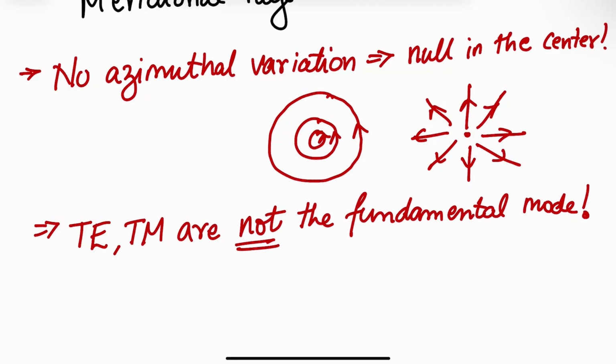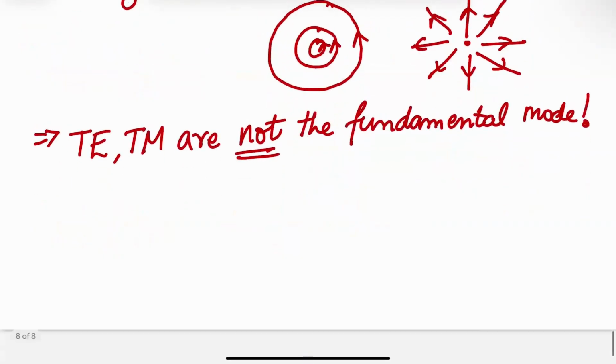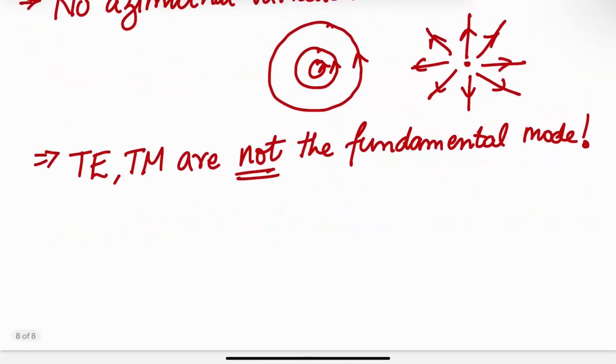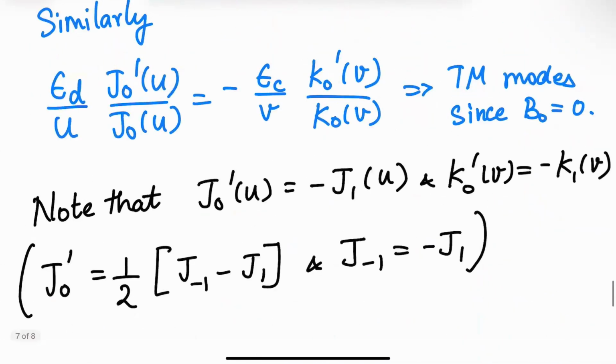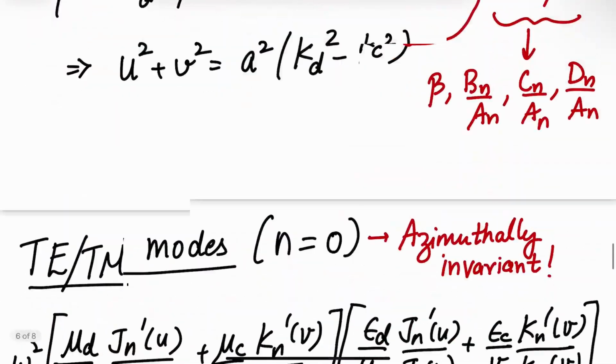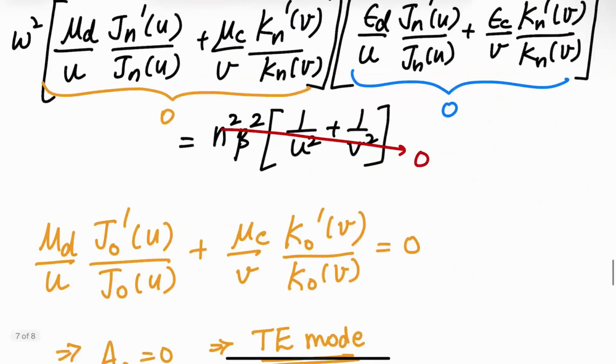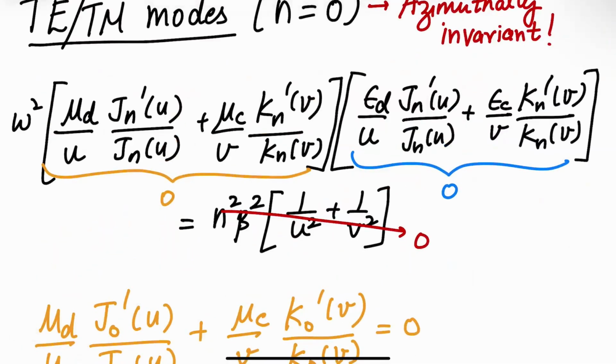And the reason behind that is that all other modes are in cutoff, so you have a bandwidth over which only this mode propagates, so it's very easy to excite it, right? And have only that mode propagate. So those fibers are called single mode fibers. We'll talk a little bit more about single mode fibers at the end, but this is a problem because now we have to actually solve the full transcendental equation in order to find this fundamental mode. Right? The simplified version of the transcendental equation where the right-hand side went to zero is not good enough.